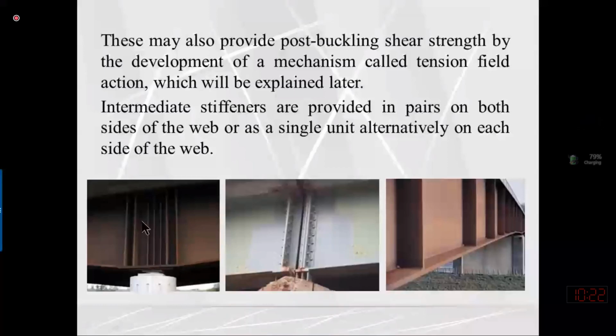Why have they decided on seven bearing plates? Because the number of bearing plates and the size of the bearing plates are based upon the applied shear. Maybe at this reaction, the applied shear force, or this end reaction, is very heavy or very large. You can see that these are two separate plate girders. They are discontinued over here, and the bearing section is comprised of two angles on one side, and one double angle is also provided on the other side.